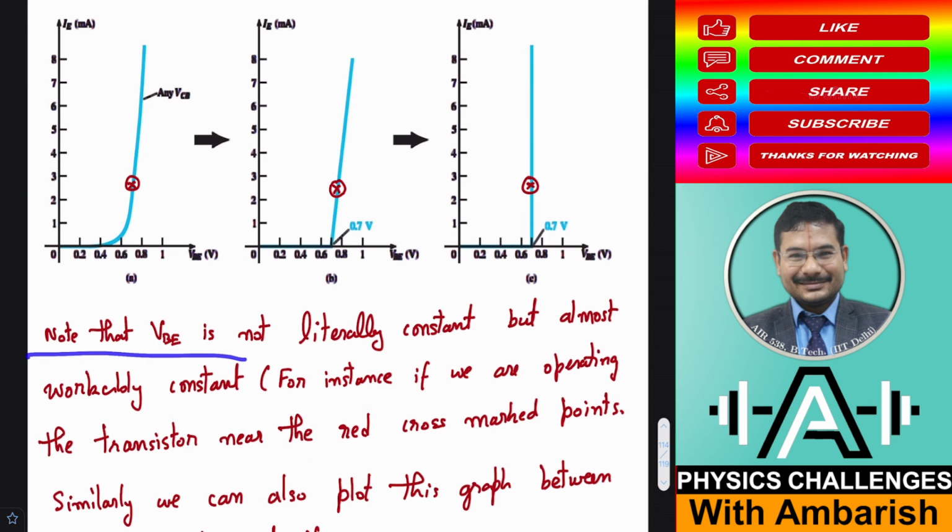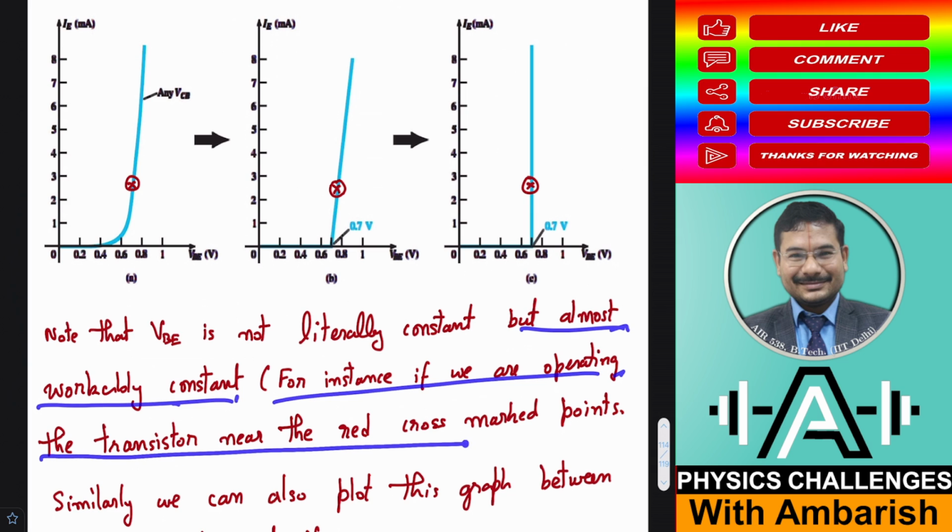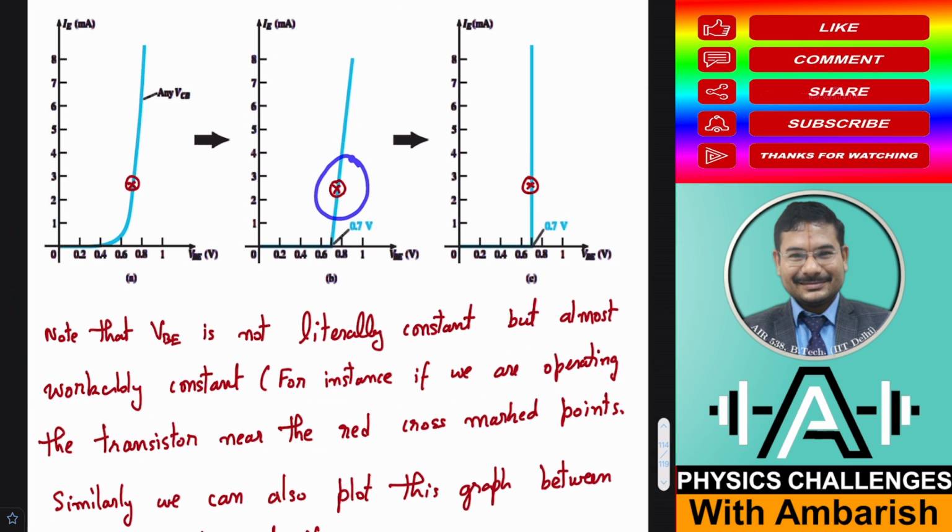Note that VBE is not literally constant, but almost workably constant. Okay. So this is not constant actually. You see voltage is increasing a little bit, but if you are working somewhere over here around these voltages, you can assume this is 0.7 volt for modeling the behavior. Okay. So it is workably constant, almost workably constant. For instance, if we are operating the transistor near the red cross mark points, so these points we are operating.